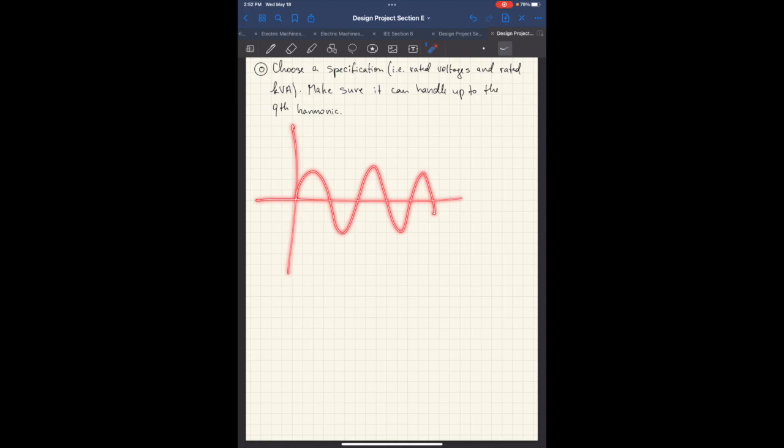That's a fundamental frequency. But what if we had, for example, a square wave, right? A square wave has harmonics. It has a fundamental frequency that you can identify, but it also has some additional harmonics involved in it. So basically, if you were to add these harmonics, you get the square wave. If you just take out the fundamental frequency, you get a sine wave. Okay? Have you guys talked about this in series, Taylor series, Fourier series? None of that sounds like gibberish, right?